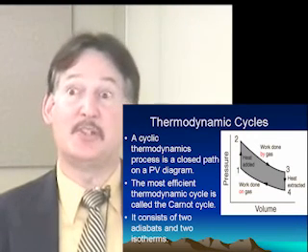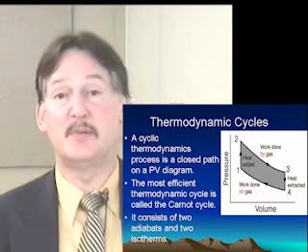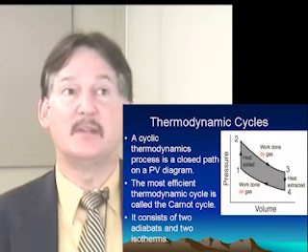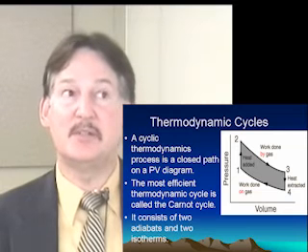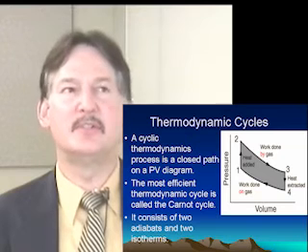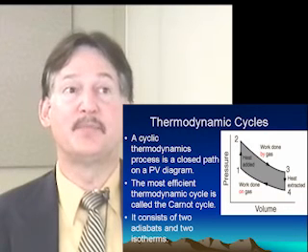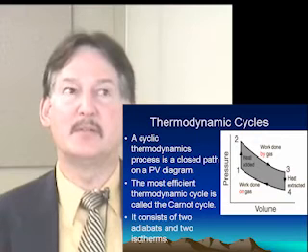Finally, back, remember this is a cycle, so a cycle means we have to return to our starting point, so we have to go from step 4 now, back to step 1 to complete the cycle. That means we are repressurizing, volume is decreasing, and the temperature, again, it looks sort of a gentle, increasing, sloping line, so it looks like an isothermal, a constant temperature contraction while the pressure goes up correspondingly. Again, that would be a Boyle's law relationship.